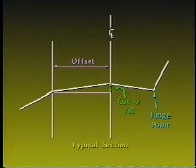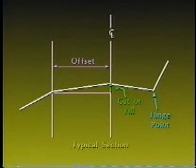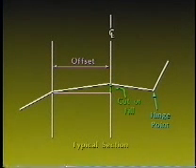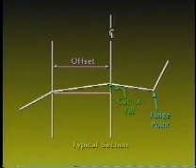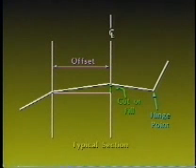When the alignment is complete and stationed, the second part of the design process begins. A typical cross-section for the work is designed. The typical cross-section represents a view of the finished work at right angles or radially to the control line. Shown here is the typical section for our highway project. Dimensions or offsets are given from the center line to hinge points or changes in grade on the section. Typical hinge points shown here, moving from right to left, are located at the top of cut, flow line of ditch, center line, shoulder, and toe of fill.